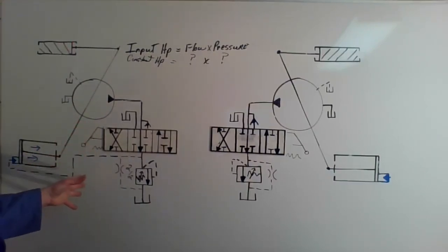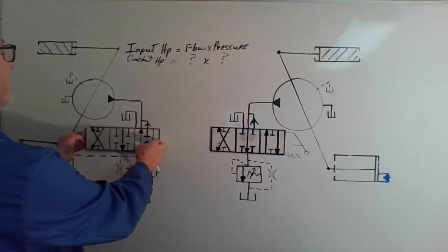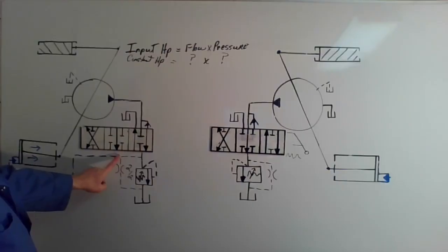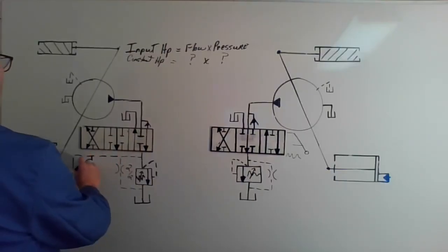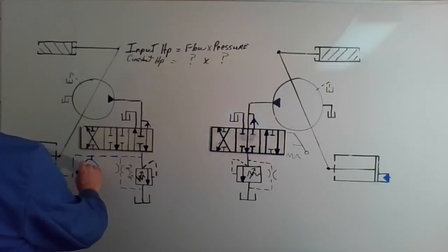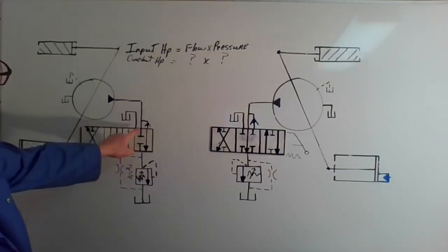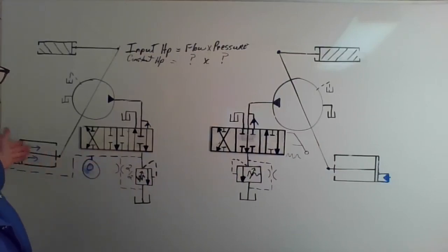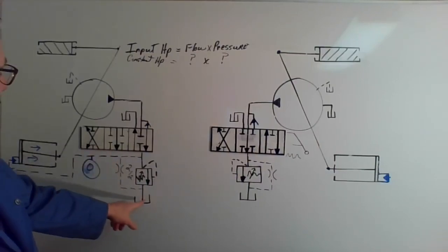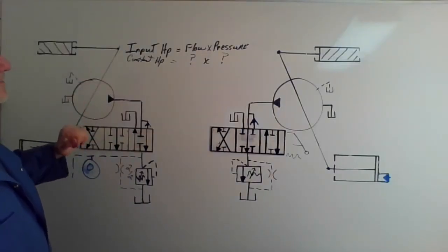So this is called negative flow control pressure, and as soon as I function the DCV, again, that pressure that was in here, for all practical purposes, the 212 that might have been in there to de-stroke that, physically drops to 0 because there's no more oil going to that, and in fact any oil that was trapped in this stroking piston is allowed to bleed off. So as soon as I move the DCV, this pump upstrokes.